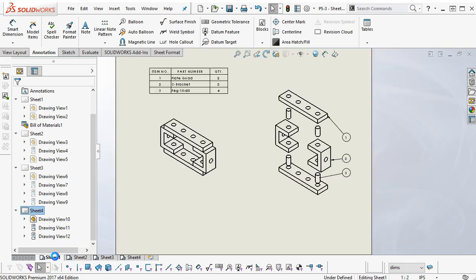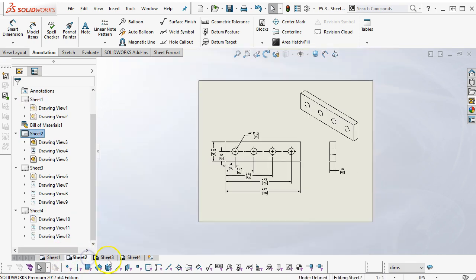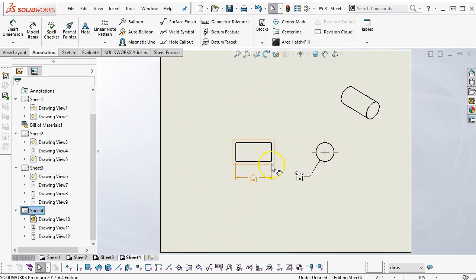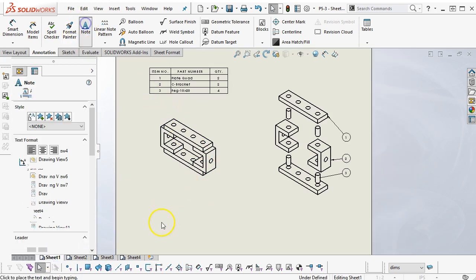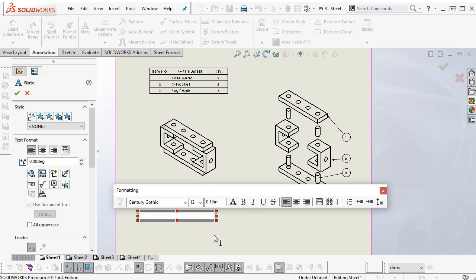We set our parts. All right, so we have now a drawing package that has, this is how it goes together. These are the parts that we're making for it, but we don't have any notation on this sheet. So at the upper limit, or at the upper end of the capabilities, I would have all of these parts with their individual file properties populate the title block myself. Again, for expediency, we're going to go into Note and start to think about what items are going to be beneficial to have. So first pass through, if this isn't already set up for us, and it's not, then we'll think about the file name.